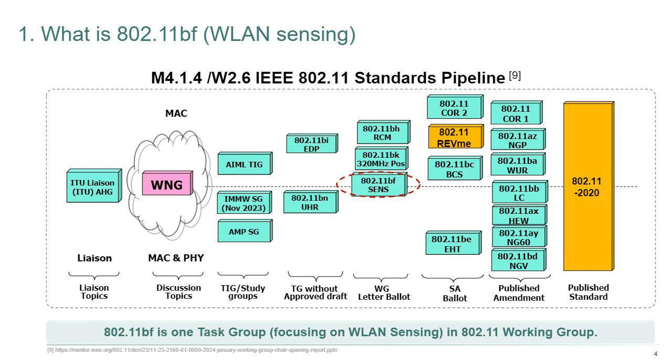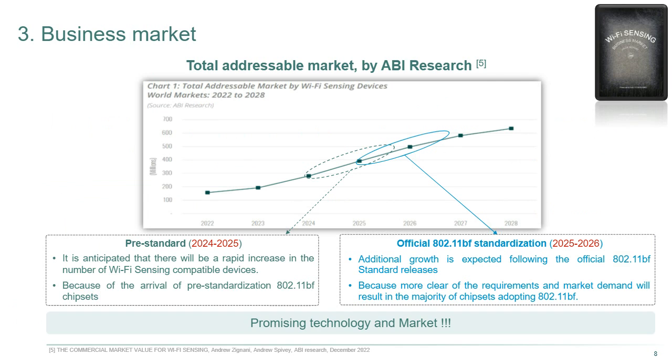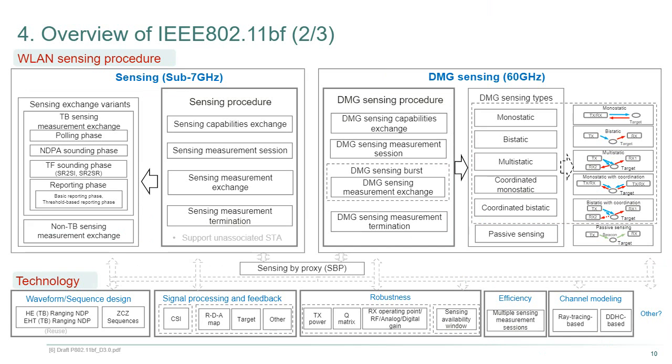Yeah, so I think I generally mentioned this part. That's the basic feedback types. It's not only RSSI. The basic report is the CSI, channel state information, including the IQ part of the channel measurement. So the CSI is our fundamental report, and also the only report type for sub-7 gigahertz sensing. For millimeter wave, we have more report types.